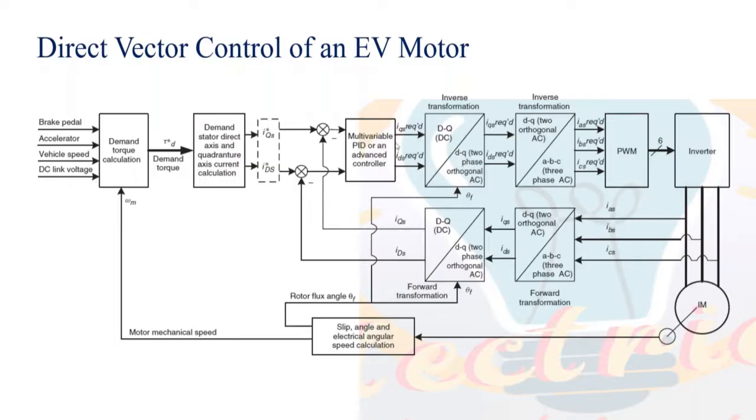Now, especially the PMSM motors and induction motors, all these motors use field-oriented control, because field-oriented control considers the motor, either an induction motor or PMSM or any type of motor, as a separately excited DC motor. I hope you know what a separately excited DC motor is. In a separately excited DC motor, we control only two things: flux-producing current and torque-producing current. So you have the two currents flowing there.